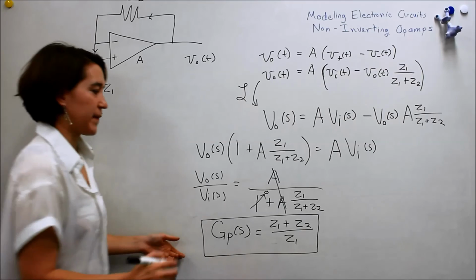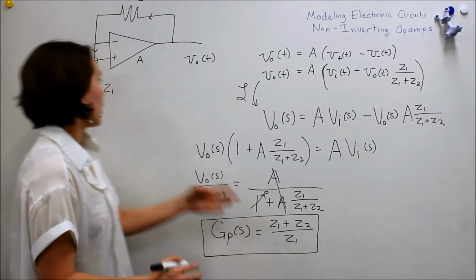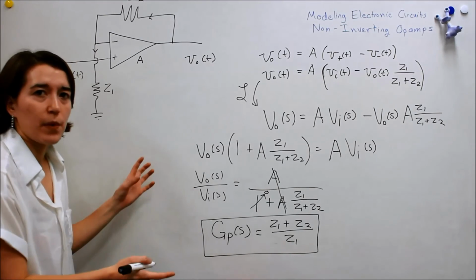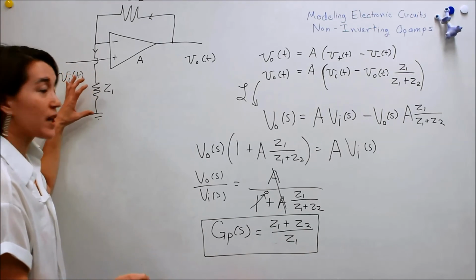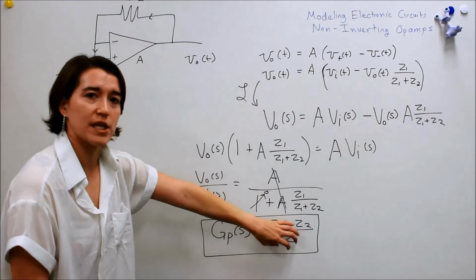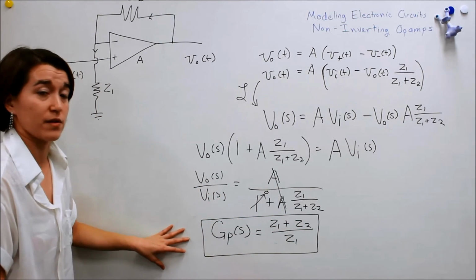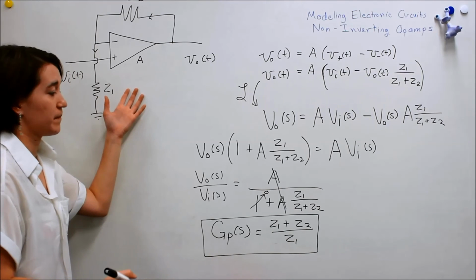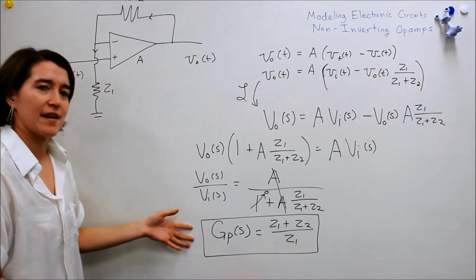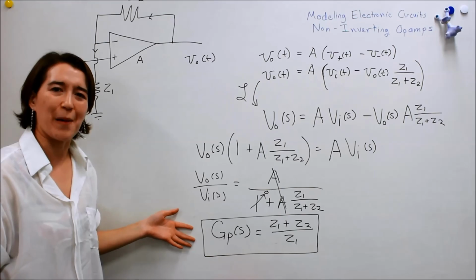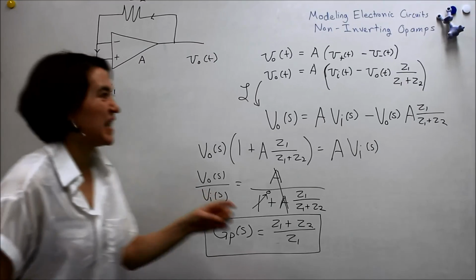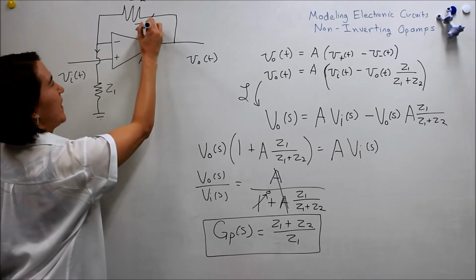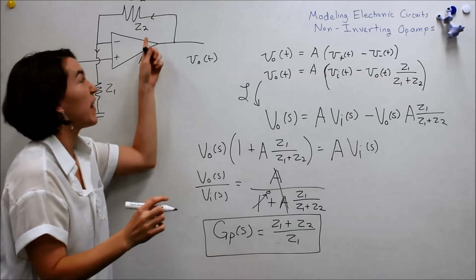And like the other op-amp equation, if we know these impedances, say it's a combination of resistors and all the other components, we know the impedance of this branch, we can plug that value into here and go from this expression. So this is a general expression for this non-inverting op-amp structure. And that's how you do the transfer function for a non-inverting op-amp. I just realized that you can't really see this. This was Z2. So just rewatch the video and just pretend that that's there, okay?